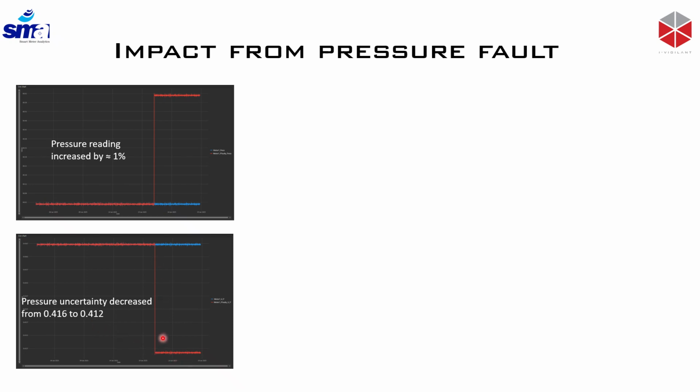The decrease is because the pressure transmitter uncertainty is 0.25% of span, and when we look at the percentage of the actual value, it actually increased the uncertainty because the pressure reading is increased. Now, the uncertainty value does not describe the bias at all. It purely looks at the value of the pressure that we have at the moment.